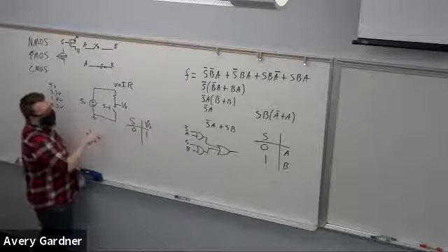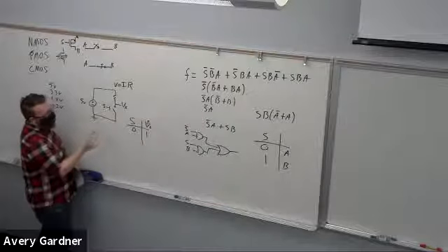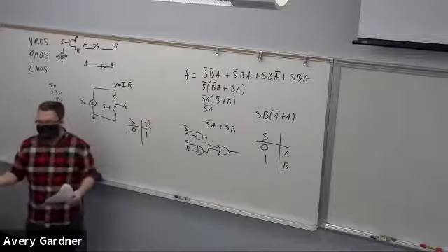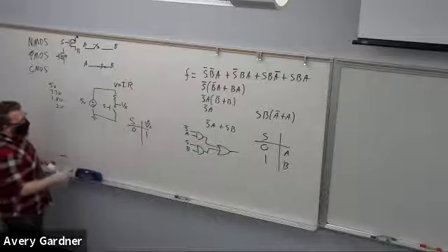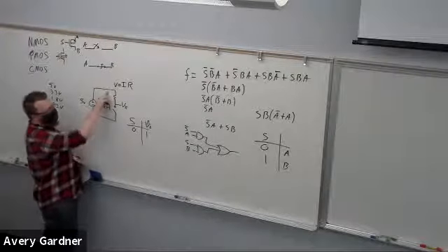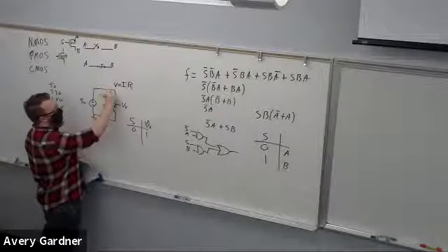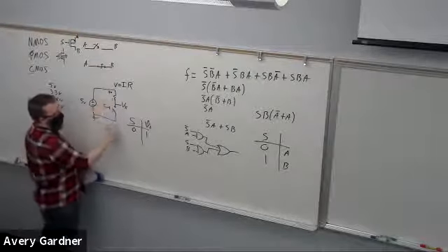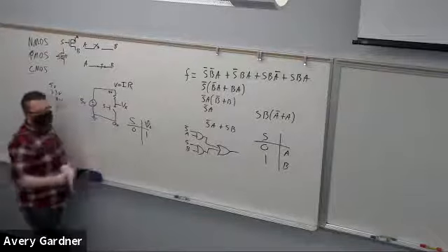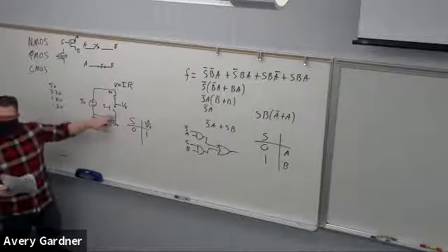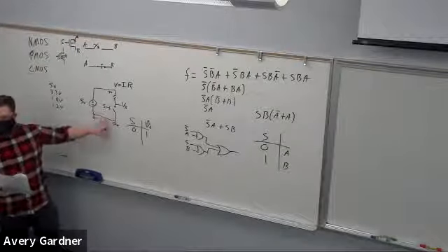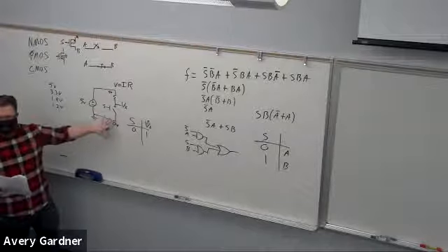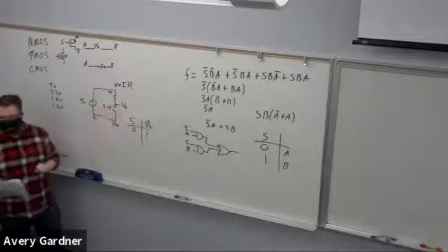Now your voltage drop, well, we could go through a whole bunch of Ohm's law stuff for this, or I could just point out, you have voltage up here at 5 volts, blocked by a resistor, and here we have ground at 0 volts with no resistor. Ground with no resistor will always win. So it just becomes 0.